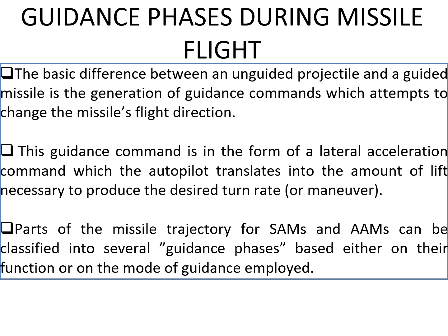The guidance command is nothing but the lateral acceleration command, which the autopilot translates into the amount of lift required to produce the desired turn rate, which is the rate of change of velocity, so that it can be changed in the x, y and z directions.